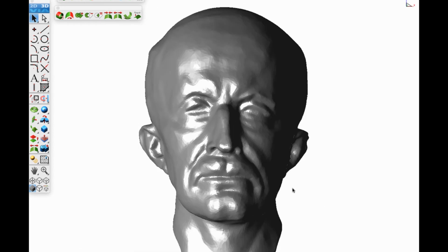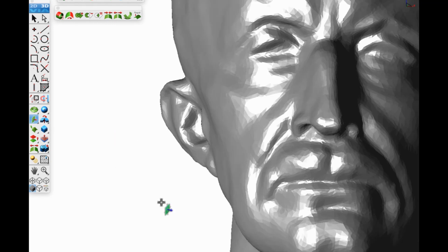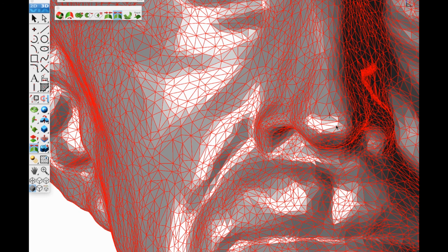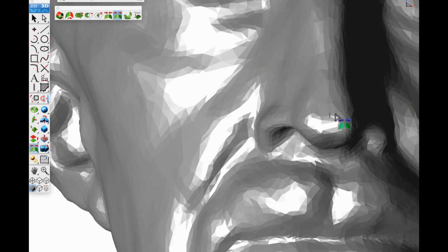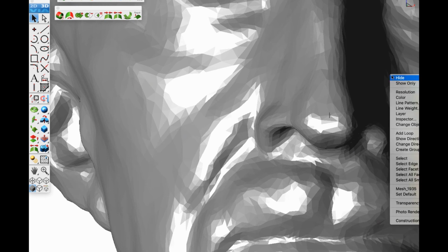Now let's jump into the front view, and let's place another cutting plane across the center of our statue. And this time we'll select an X station, and we're going to put it along the nose here. And again, select the split tool, select the mesh, select the cutting plane, and let it slice the head into two pieces.